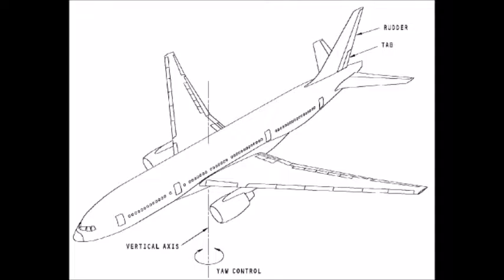The rudder is responsible for the yaw control. The pilots make a manual yaw correction with the rudder pedals. The autopilot does not control the rudder during most phases of flight. When the autopilot is engaged during the approach and landing phases of flight, the autoland function commands the rudder. The backdrive actuators then backdrive the rudder pedals.